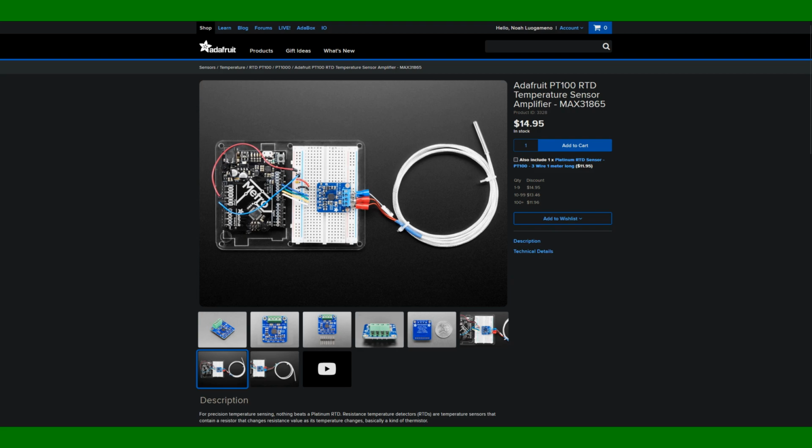I think that would be more useful than the type of sensors that we used in our most recent workshop together, because that would just be inside of the CubeSat, and you would only be getting the ambient temperature inside the CubeSat. You can still do that. Different materials would probably heat up the inside of the CubeSat at different rates, but I think this would get you a more accurate reading of the material itself.